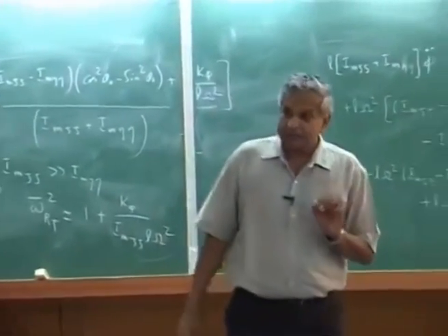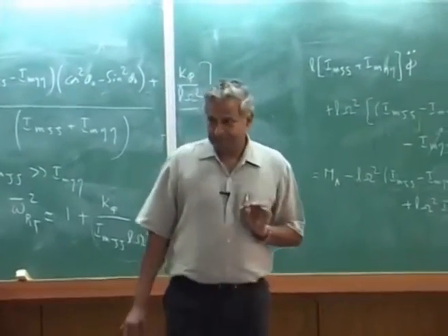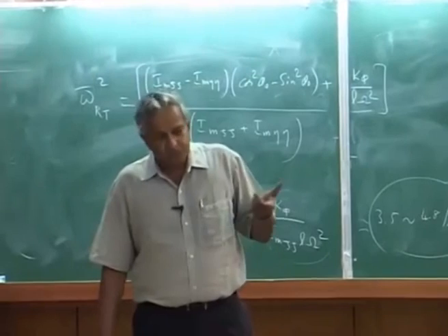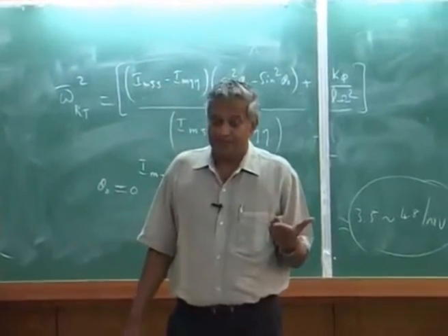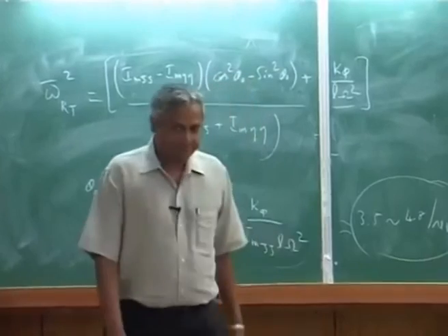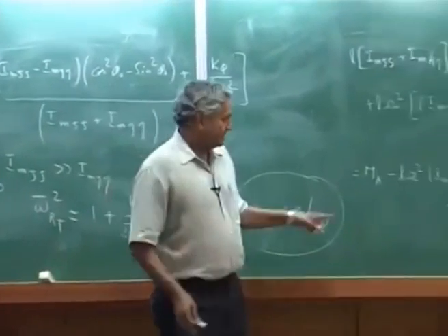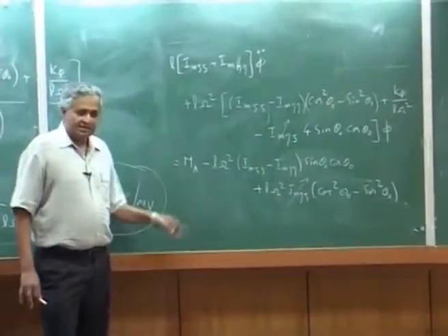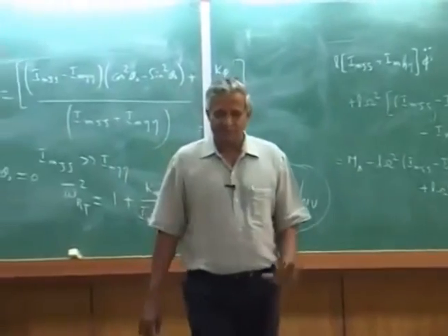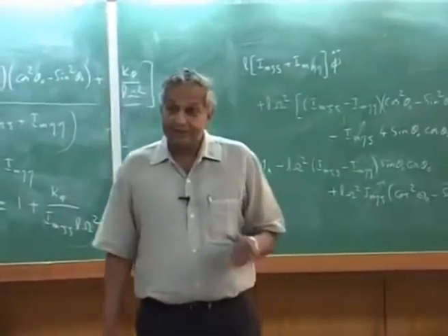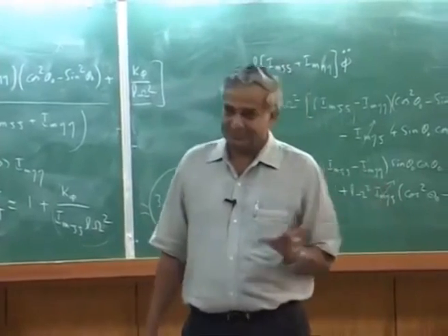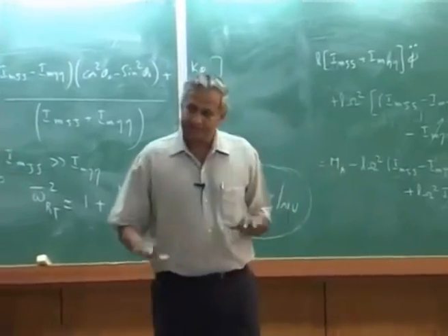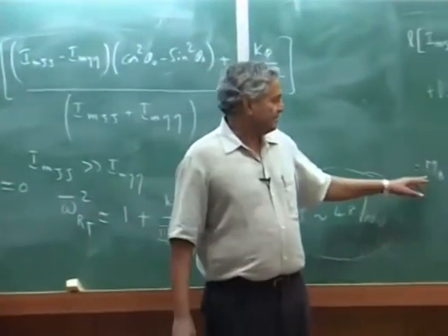But if you ask what about the damping in torsion? Okay, lead lag we discussed. The damping is very small and usually an external damper is provided. In torsion, the main damping comes because of aerodynamics. Usually it is about 10%. That's why there is no damper provided in torsion. Okay. Flap is heavily damped, lead lag you put an external damper, torsion is also damped out,